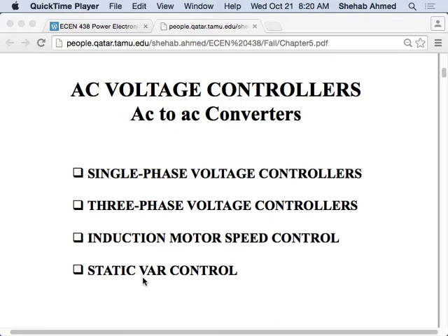So sometimes when you're consuming lots of reactive power, you bring lots of capacitance into the system. Then you switch them out when reactive power consumption goes down. So you've turned off the motors, you've turned off the transformers, right? You've disconnected these inductive, reactive power consuming loads. So this turning on and turning off of capacitors will cause these inrush currents.